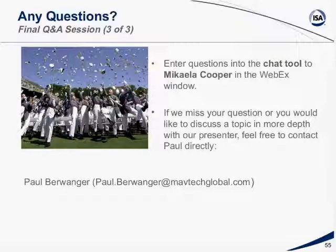Or you've got what happens a lot: a piece of equipment or a transmitter that hasn't worked for 6 months, and it's been shelved for that period of time. Well, if something's been shelved for 6 months, chances are you don't need it as an alarm. Just take it out of the system. If you live without it for 6 months and you hadn't thought it important enough to fix, just take it out of the system. It's no longer an alarm, so you don't have to worry about it.